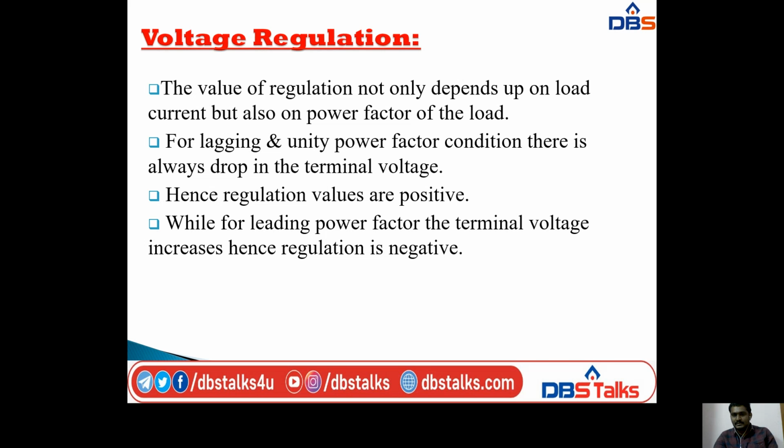For lagging and unity power factor conditions, there is always a drop in the terminal voltage. I already discussed these things: we have three types of load power factor. One is unity power factor, another is lagging power factor, and another is leading power factor. So for lagging and unity power factor conditions, there is always a drop in the terminal voltage. Hence, regulation values are positive.